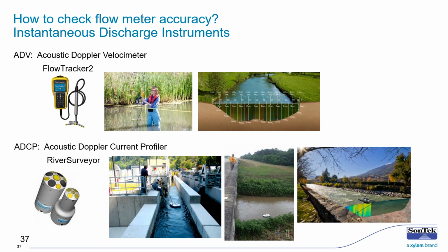In the top case, the person gets in the water and moves from the right to the left bank and measures at points along with the depth. And then these measurements are gathered, thrown into a calculation. I'll show you that in a second. And an accuracy number, and the uncertainty around that accuracy number, is also output.